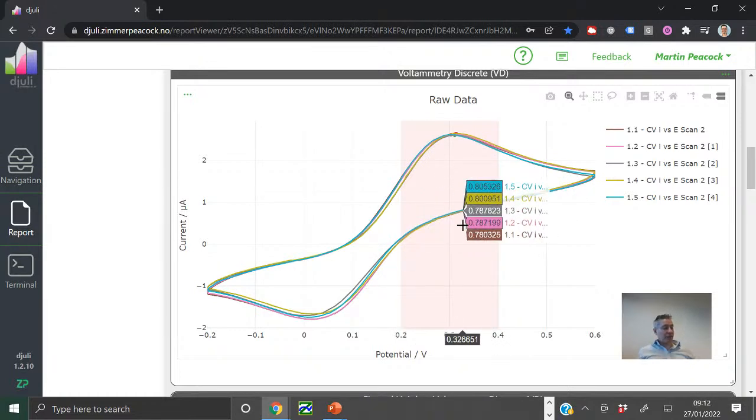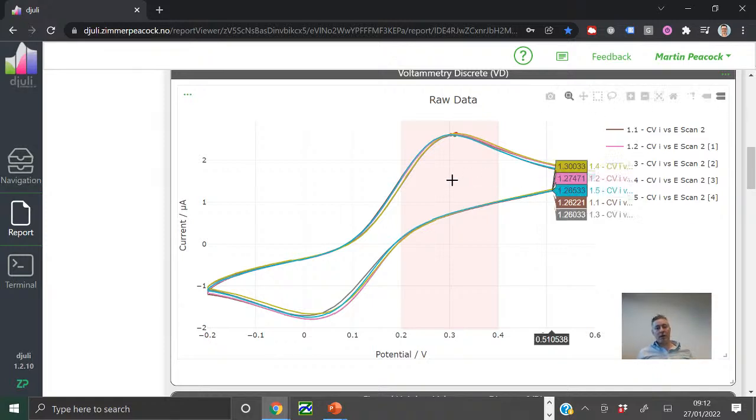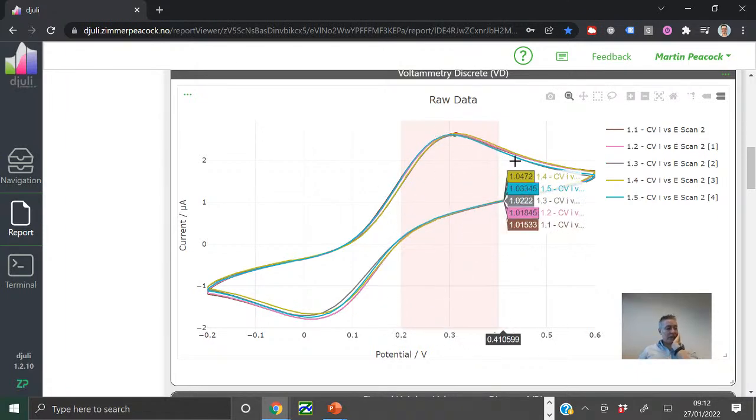So for me, we can analyze the production in a way that you actually use the sensors in the final assay. It makes the testing equivalent to the way the sensor, or the electrode, will actually be used. The reason I say that's important is because if you just measure resistance, then yeah, you might hit the resistance specification, but it didn't tell you anything about whether you were able to then use that electrode, you know, necessarily in your voltammetry.